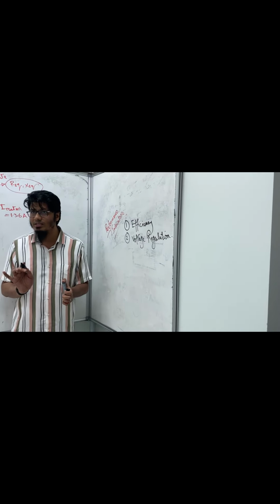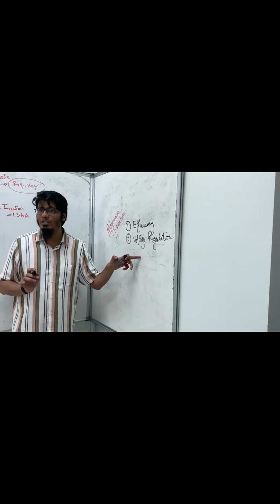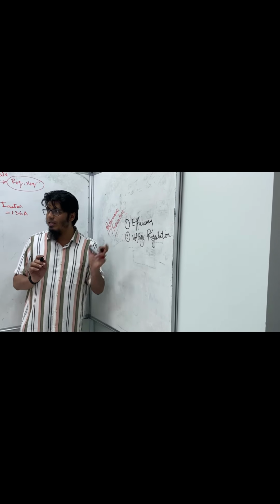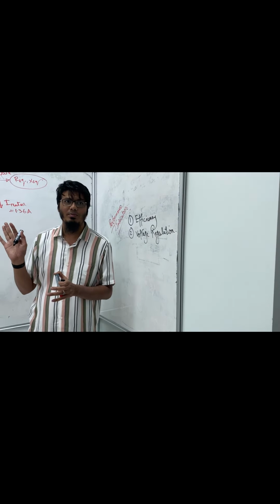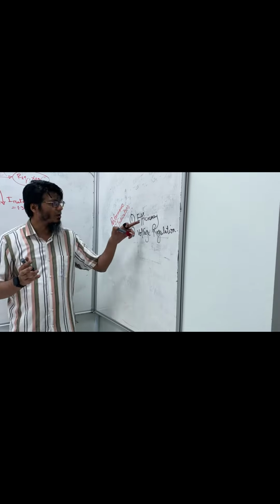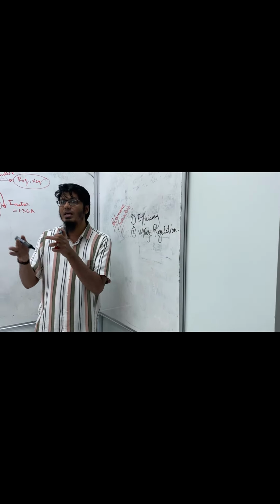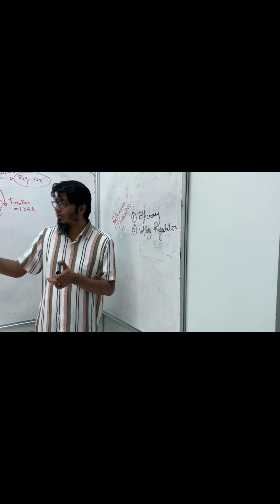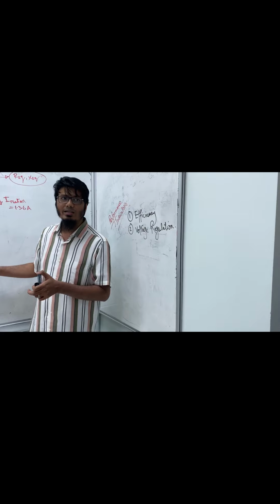Now you have to understand: if you want to find efficiency or voltage regulation, can you find them using these tests, open circuit test and short circuit test? You can never, right? Why? Because to calculate both of them you need secondary side power or secondary side voltage. But in one case the secondary is open, so current is 0.